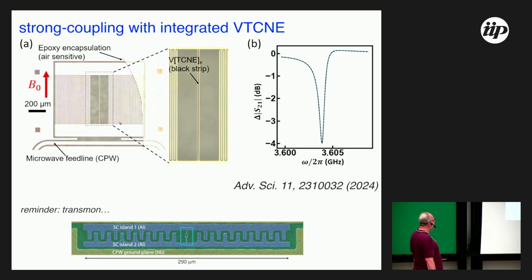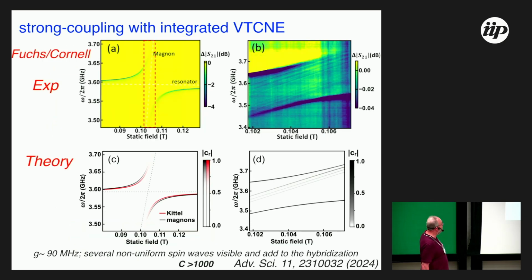And the reason for that is it's a lot easier to deposit that than something like YIG, which destroys the superconducting thing. You'd have to put the superconducting thing on top of it versus the other way. There's been a lot of revolution in the development of this organic ferrimagnet, mainly the ability to encapsulate it so it doesn't decay very rapidly with time. This is using encapsulation procedures that are very similar to how you encapsulate the OLEDs that are in the phone or in televisions, so that you can use organic devices for people-relevant timescales of years rather than research-relevant timescales of days. All right, so here's the resonance of that superconducting cavity, and here's the strong coupling demonstration.